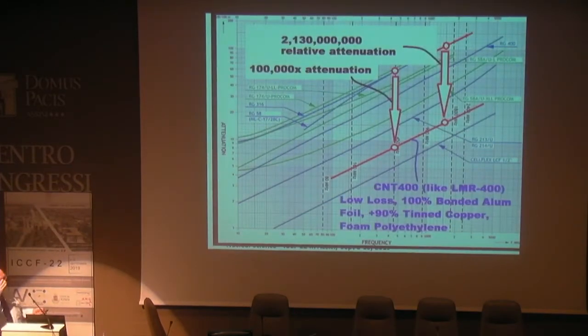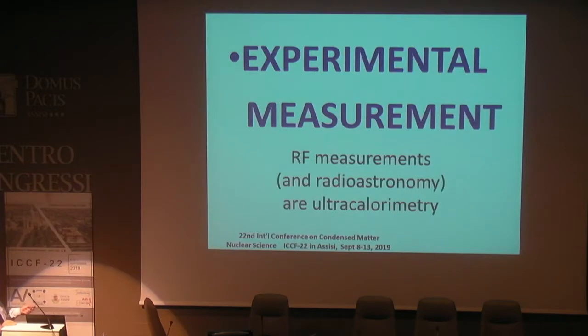But the biggest problem is transmission lines. And it turns out that if you're a radio amateur like I am and you take your RG8U to connect it up, the losses are incredible. So we had to buy military-grade material, and we end up coming down by quite a bit. We decrease the attenuation by 10 to the 5th. If you do it, we'll give you more tips on how to handle that.